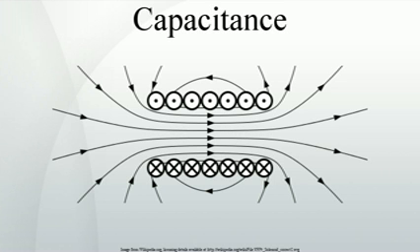In particular, to circumvent the mathematical challenges of the spatially complex equipotential surfaces within the device, an average electrostatic potential experienced by each electron is utilized in the derivation. The reason for the apparent mathematical differences is understood more fundamentally as the energy of an isolated device, self-capacitance, is twice that stored in a connected device in the lower limit n equals 1, as n grows large. Thus, the general expression of capacitance is as follows.